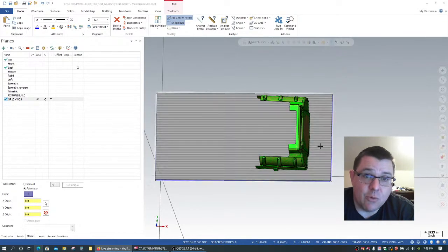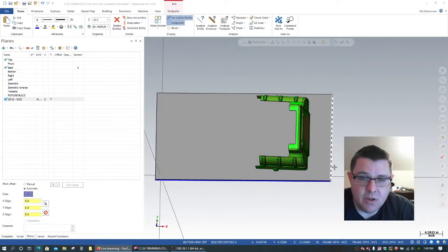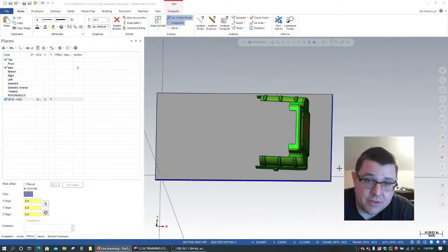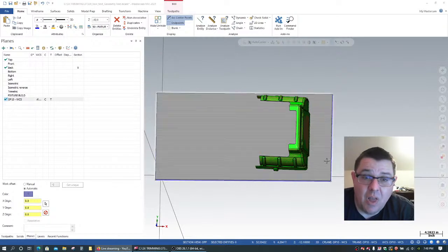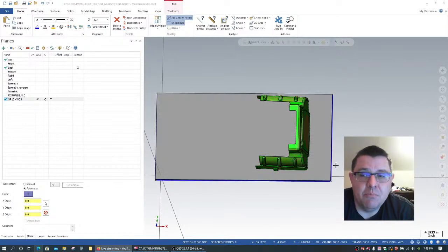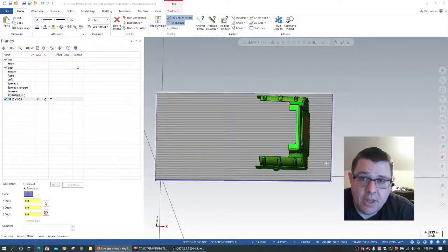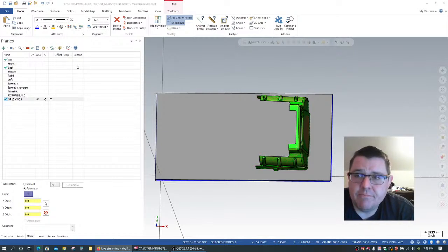And then how do we machine that? How do we do some surfacing toolpaths, like OptiRough, some of that kind of stuff, to take a solid block of Ren shape or foam or some other type of fixturing material, wood maybe, and start cutting it out so that we can start actually building a 3D vacuum fixture. So, all right, we'll get into that next time.